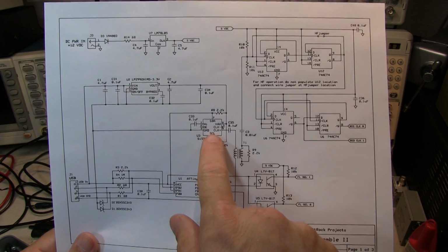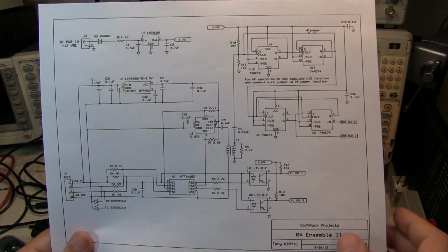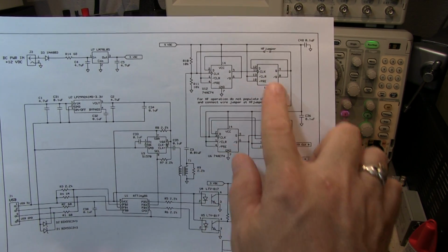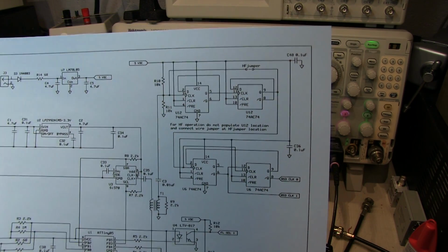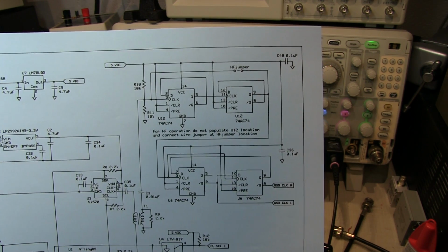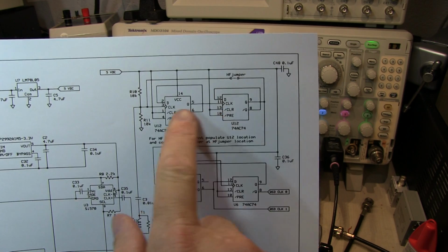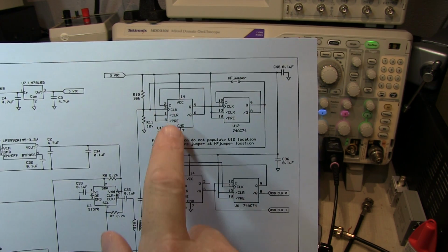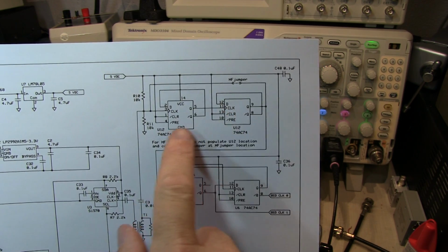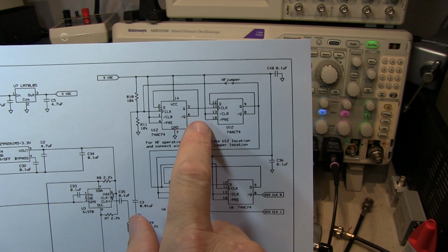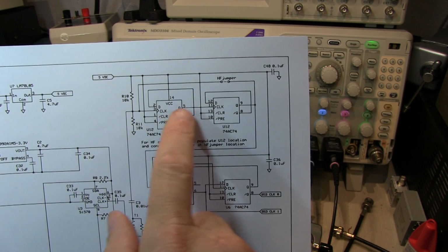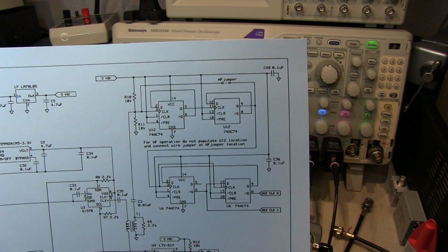Okay, we've seen how the high frequency clock is generated by the Si570, goes through this transformer, and then goes into the clock dividers. These dividers are what create the quadrature clocks that are used by the Quadrature sampling detector. This is the optional divide by 4, and it really is just two divide by 2s cascaded. A simple D flip-flop with the inverting output fed back to the D input will divide a clock frequency by 2. So we do that twice, and that would be the divide by 4.